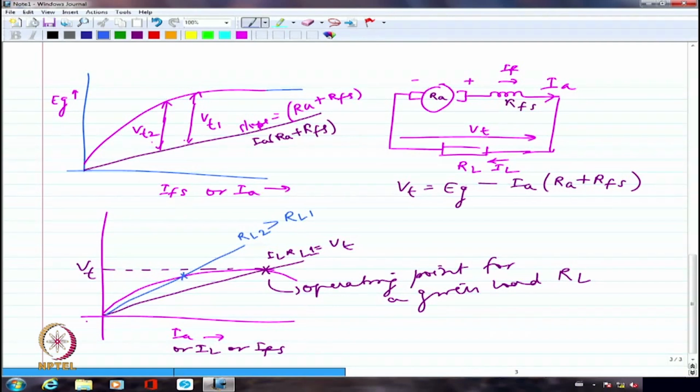What he means is, I should have probably drawn the characteristics increasing, and after that it should start dropping. Hardly ever there should be a flat portion in the series generator. That's right. Okay, so this essentially completes our discussion on the generator operation and the generator characteristics as far as the DC machine is concerned.